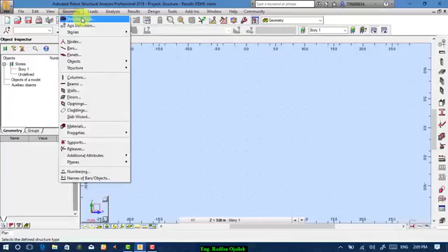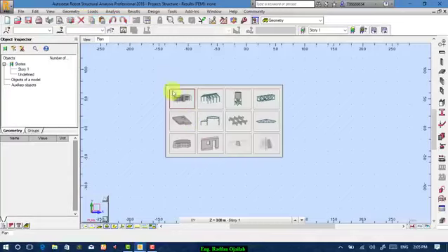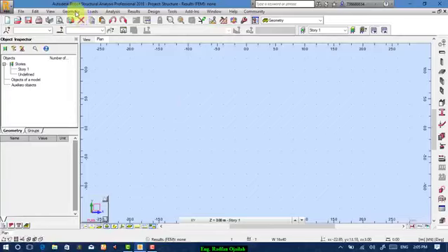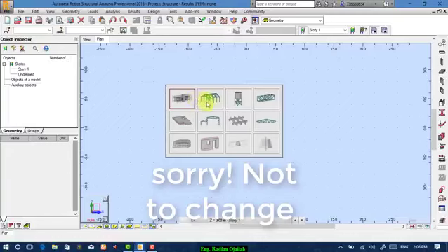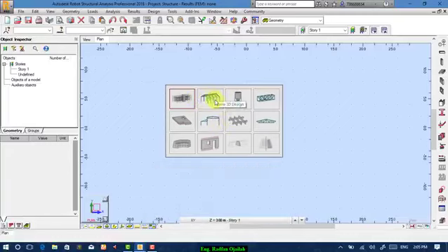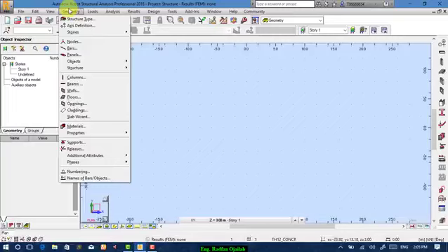Okay, and structure type. From geometry we have structure type. The structure type is the first menu that we have opened in this software. This one, you can choose it, but I advise you not to choose your structure type when designing a building, because this software reads everything differently from one structure type to another one. So choose the first one and stick to it.